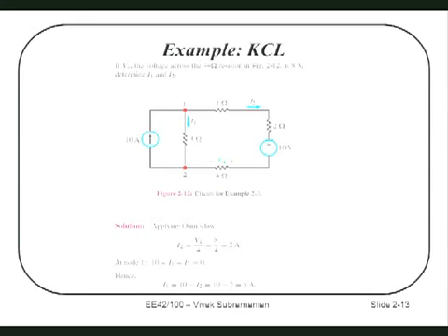Good. This is actually, I think, related to the same question you're asking me. This circuit is somewhat confusing because normally I would say current should go this way, right? Yet I'm showing the current going in. Can anybody tell me why that is happening? Yes, this current is so large that it generates a relatively high voltage across here. And so the voltage over here is actually larger than the voltage over here, which forces the current through there.